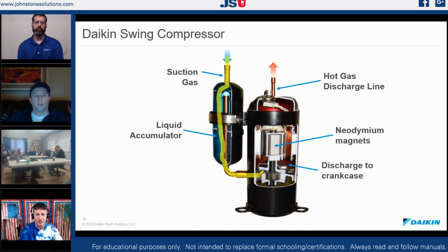And the thing with a rotary compressor of any manufacturer is on an installation, just think about that for a minute. On an installation of any outdoor unit that has a rotary compressor, if I open that suction valve first, what's going to happen to the oil in my compressor?